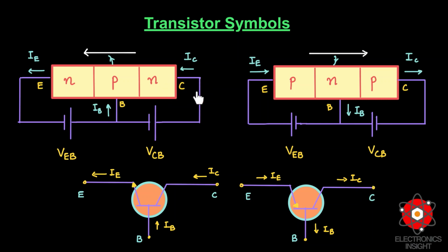Now we shall discuss the working principle of just the NPN transistor alone. Here this figure is the NPN transistor with forward bias to the emitter-base junction and reverse bias to the collector-base junction. The forward bias causes the electrons in the n-type emitter to flow towards the base. You can see here the conventional current flow is given in this direction, out of the emitter.